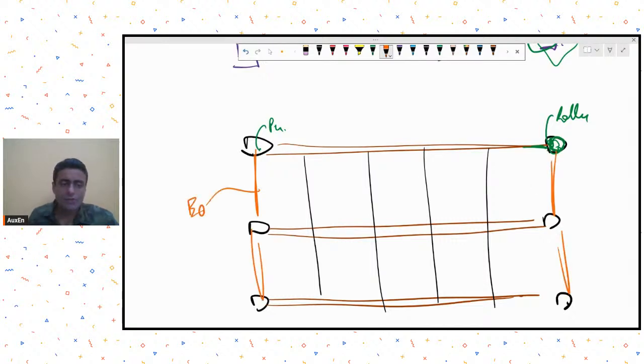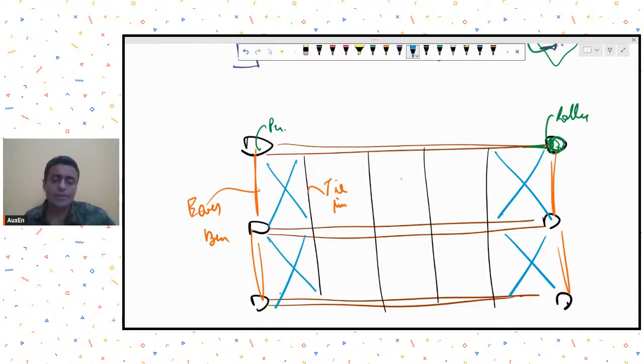So you have the eaves beam, you have the tie runner at the truss bottom chord level. To help my column not become a cantilever, I can add these additional lateral bracings. Maybe at the two eaves level, I can keep on adding lateral bracings. This will help me ensure that my column does not become a cantilever.